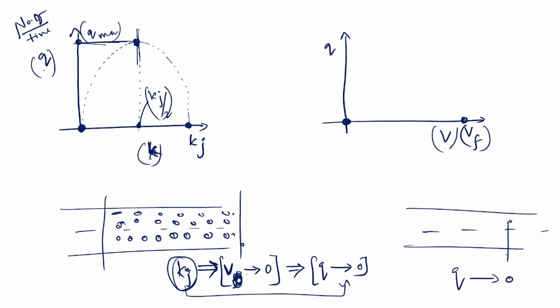When there are no vehicles to cross a particular point, Q also tends to 0 again. So when it is Vf, again it is Q zero. Again, to make a parabolic function, you need to draw like this. Again, there is a peak point which refers to Q maximum. That point will divide the parabola into two similar halves, that's why this point should be Vf by 2.